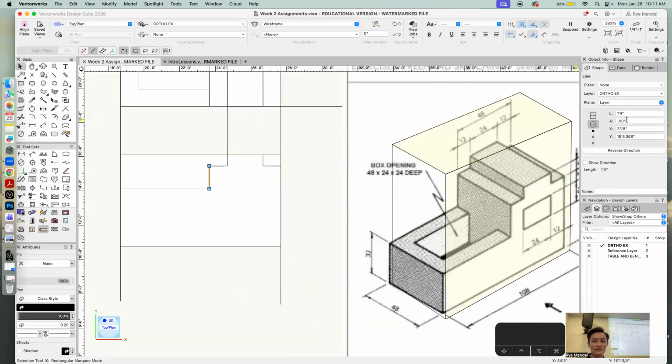An easy way to fix this is you can go over here and go to the length. You can do this super easy, right? You can just do plus 8 inches. So that was my boo-boo, right? And then you can click enter and it'll just make it 8 more inches. Or the other way that you can do it is you can click on this blue dot and then tab it over another 8 inches. Or sorry, you do another plus 8 inches.